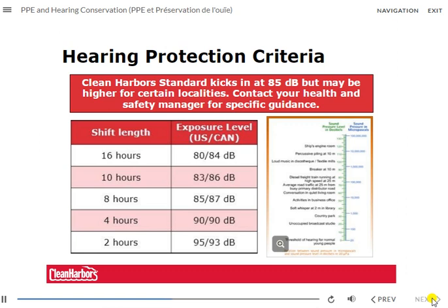TWA is used as a consideration during industrial hygiene testing to ensure tasks in an area are less than what is needed to confirm noise exposure is not a concern. In addition, as you can see on the chart, or the provided graphic, the louder the sound, the more pressure it exerts on the ear. As a result, louder sounds necessitate shorter exposure durations. When noise exposure is a concern, hearing protection will be implemented and signs will be posted signifying the danger.